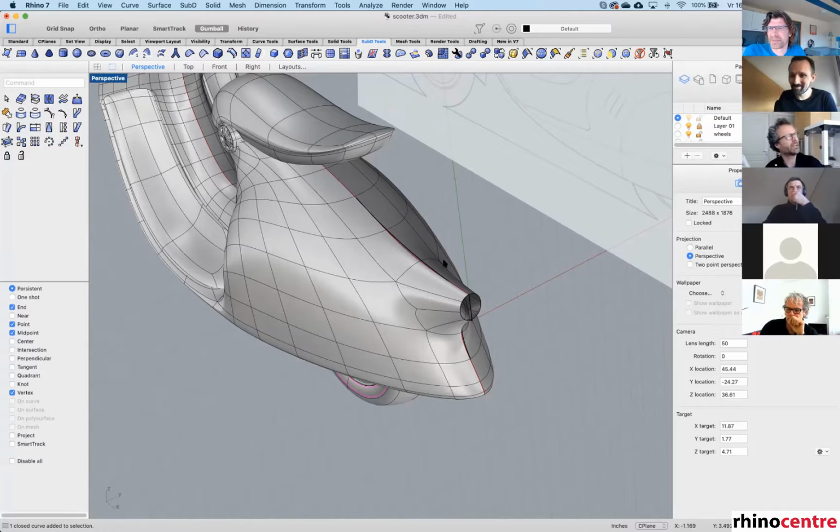Well, I'm thinking, if you use loose loft and you make a basic hull, is it then possible in Grasshopper to connect via SubD? So you transfer the loft surface into SubD in Grasshopper, and then create a shaft which connects to the aft ship via a certain routine. Then if you change your loft surface, the surface is also parametrically changed, but still has the same shaft. Would that be possible already? It depends on how far Grasshopper is with SubD.